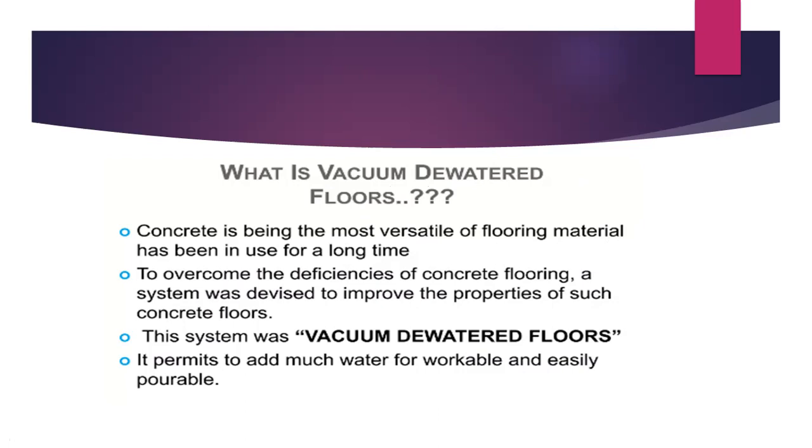The first question that comes to your mind is, why do we add water to concrete? The first reason is that it brings all the materials together. It helps the materials to bind together so that it improves the workability. In the 4th point, you can see workable and easily pourable. You make the concrete workable, which means you can easily handle it and easily mix it well.